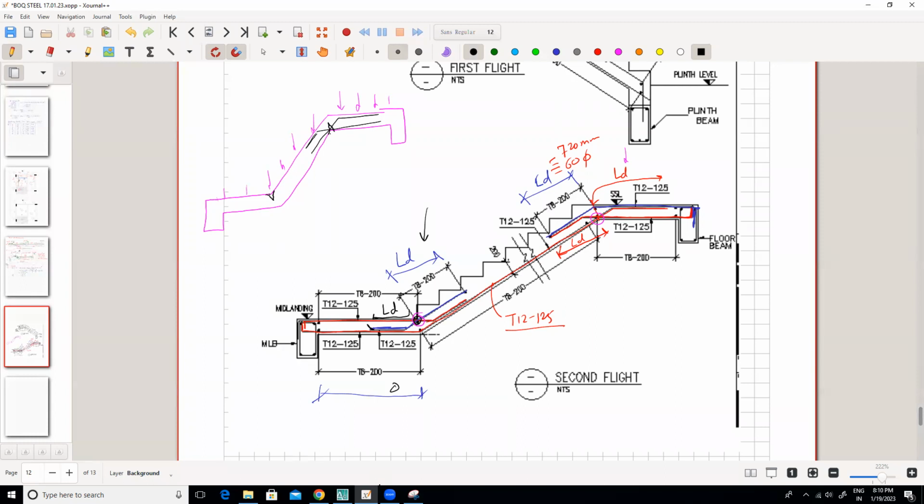So this crack, you know, is developed due to tension. And once you provide steel perpendicular to the crack direction, then that crack will not happen. Similarly, here we are taking these bars ahead. And again, this bar, the dimension you asked, we are only putting that bar to avoid the cracks. Yes, sir. So this is the detailing for the staircase.